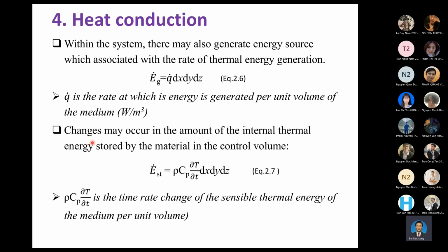The change may occur in the amount of internal thermal energy stored by the material. The material can store energy, so the stored energy equals rho Cp, which is a term of the material's ability to store energy, as I mentioned in a previous slide. You multiply with the volume also.